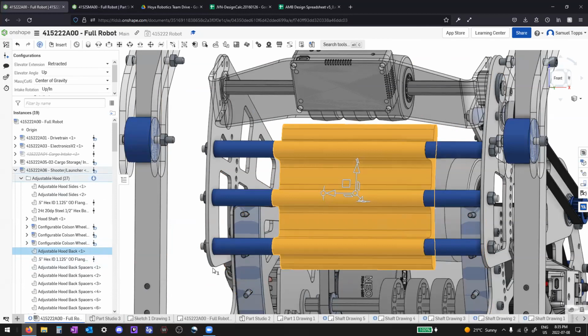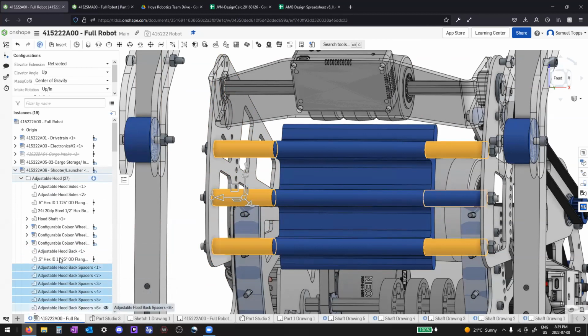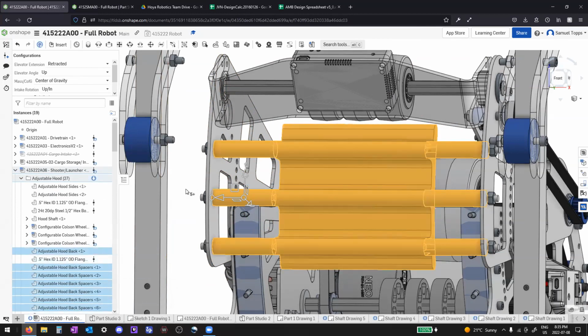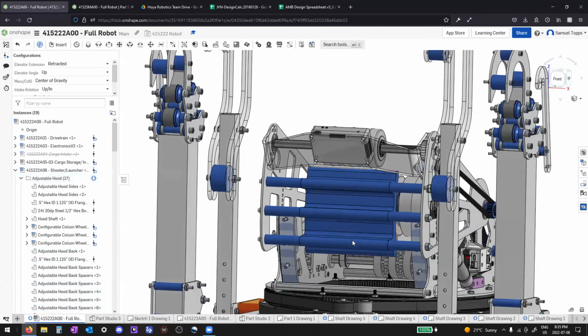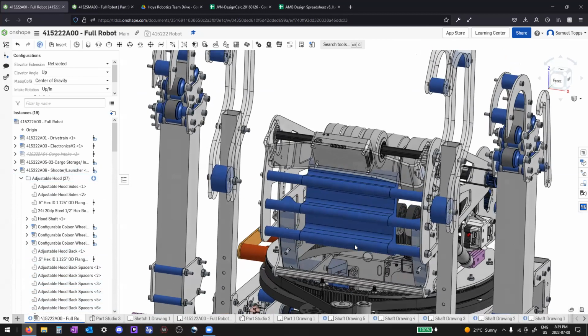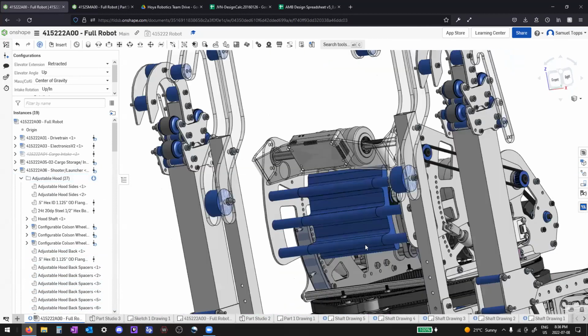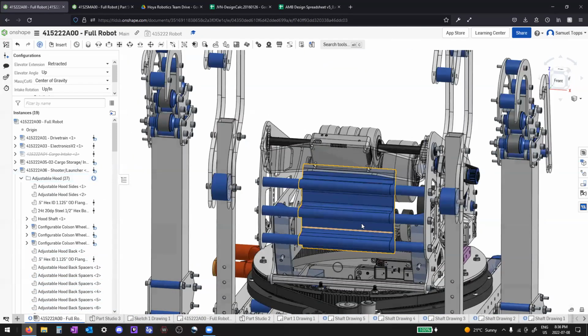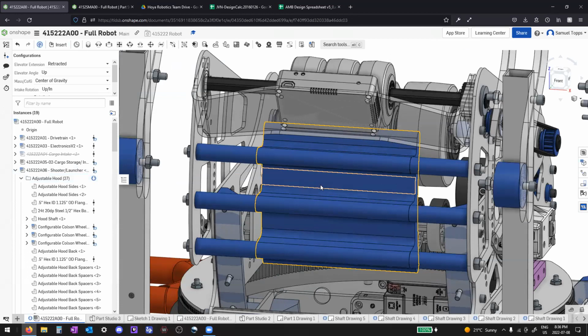That way it's printing a solid part, and the spacers are solid parts by themselves. Using that technique, you can make some really complex shapes, and they're stronger than if they had been 3D printed all at once, because if you've got a gap, it has support material and it's not quite as strong. If you can remove that and have it solid, that gives it extra strength.